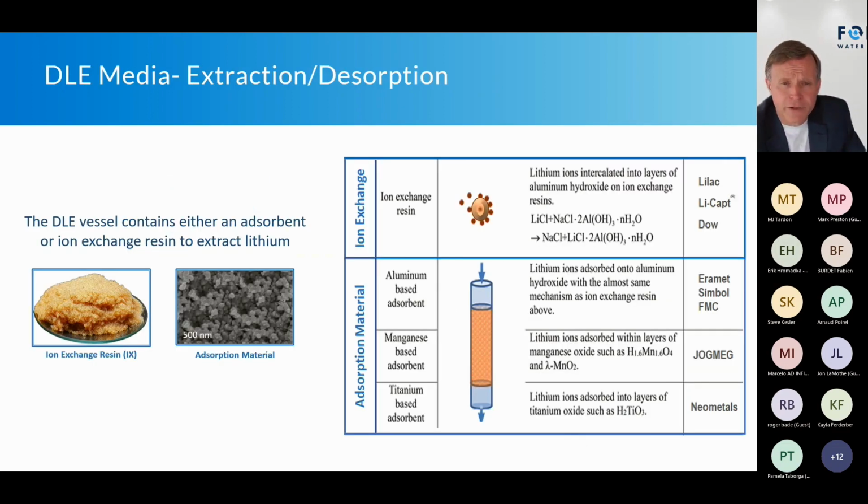The different types of materials commonly that you'll take a look at on the ion exchange is there'll be a functional group on the ion exchange, and really it comes down to the lithium will go on and another ion will come off. So typically hydrogen is the exchange ion, and the source of that could be hydrochloric acid.